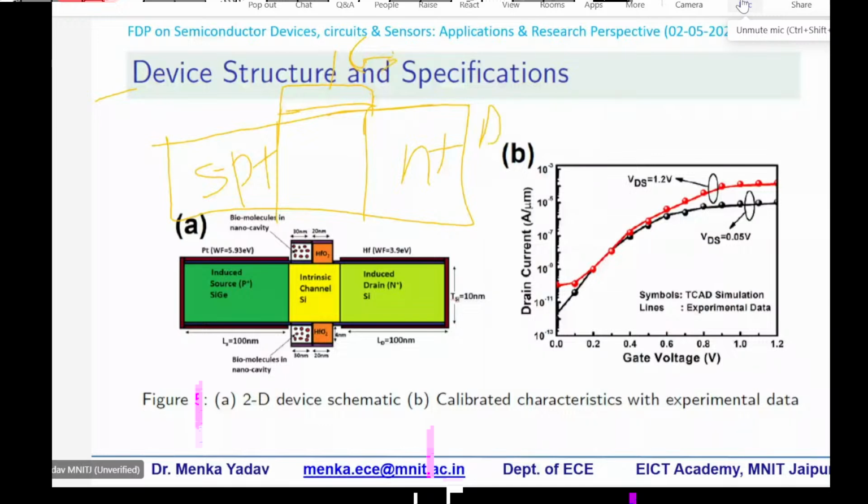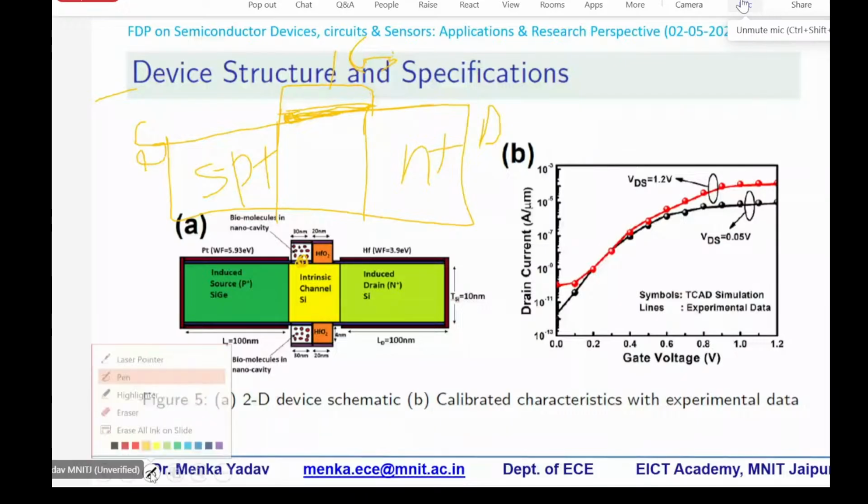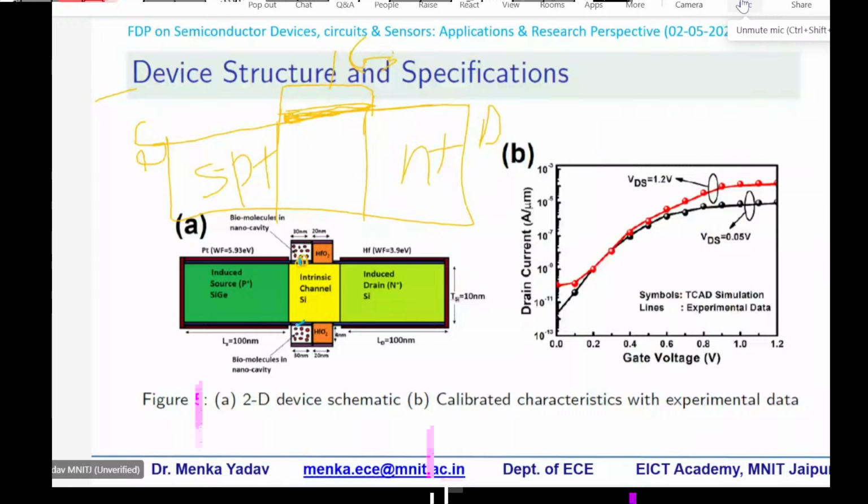So here you were expected to have the oxide layer. What we did, we have modulated this oxide layer. How did we modulate it? This is your SiO2 layer, this thin surface you can see, this is your oxide layer. Next to it is HfO2, from this to this, which is HfO2. HfO2 is also an oxide, but it is a high-K oxide.